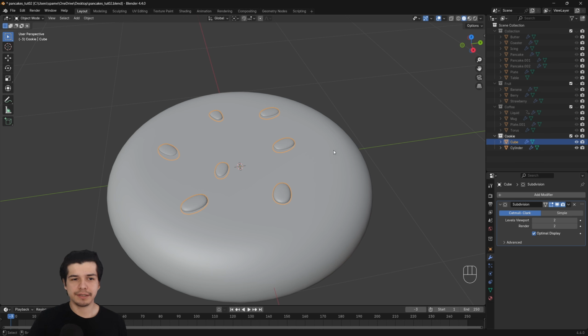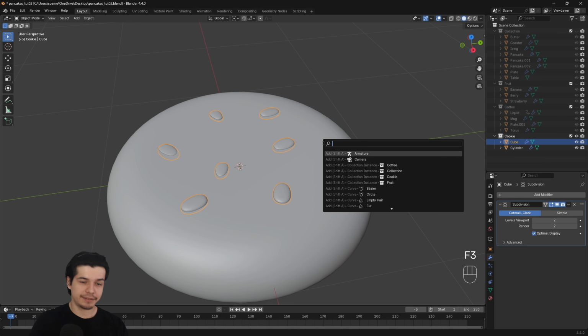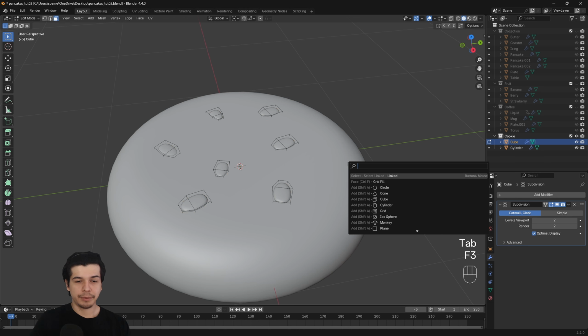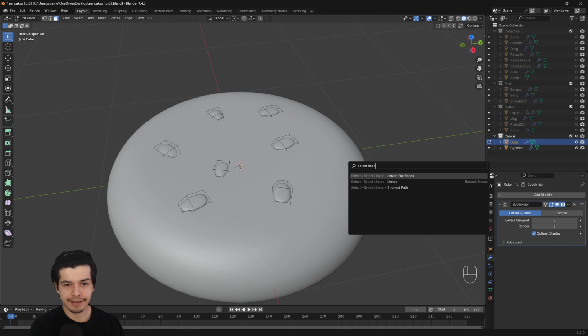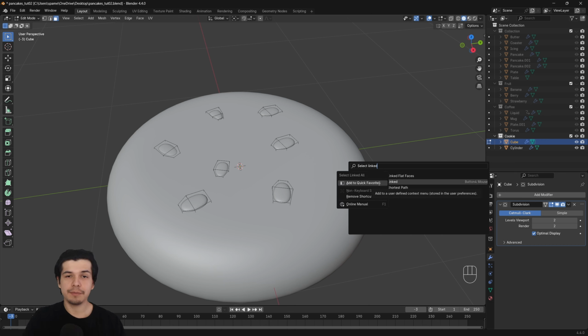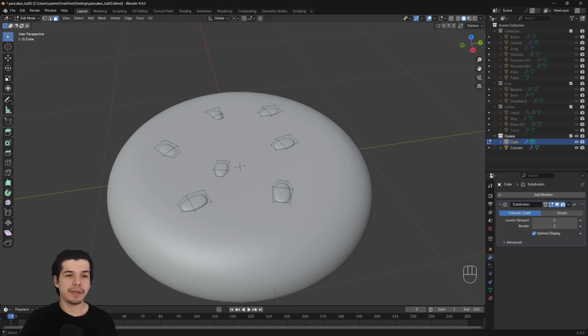how to set up shortcuts in Blender. Also, if you remember it, and I didn't say it, but if you go to select linked, which has to be in edit mode, on object mode, these functions are available in different modes, so we have to be in edit mode, and select linked. And I right click and I can put it to quick favorites as all the functions before. So you can access it very easily even without a shortcut.